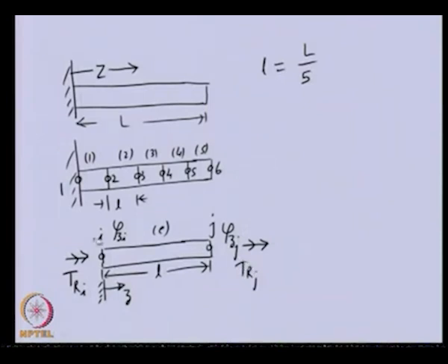So, this is an element of the shaft system for torsional vibration, and you can see that at each node there is one field variable, that is the angular displacement. So, this particular node is defined by a single field variable for this problem.